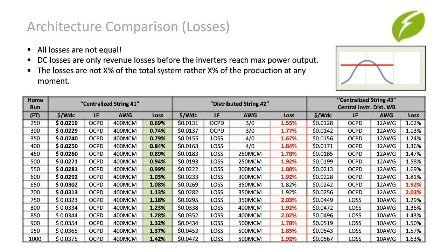So which is better? Well, you can offset DC losses, so using the PV source or output circuits to make up that home run we calculated will result in less losses than if you ran the AC conductors, which means systems 1 and 3 are better when we're discussing losses. They're both the centralized architectures.